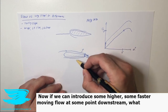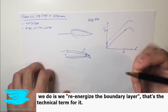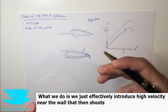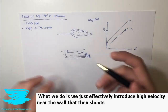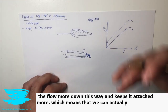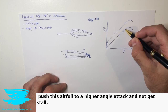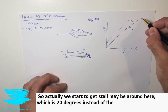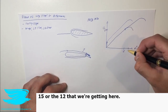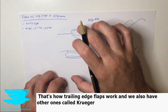Now, if we can introduce some faster moving flow at some point downstream, what we do is we re-energize the boundary layer. That's the technical term for it. What we do is we just effectively introduce higher velocity near the wall that then shoots the flow more down this way and keeps it attached more, which means we can actually push this airfoil to a higher angle of attack and not get stall. So we'll actually start to get stall maybe around here, which is 20 degrees instead of the 15 or instead of the 12, let's say, that we're getting here. So that's how trailing edge flaps work.